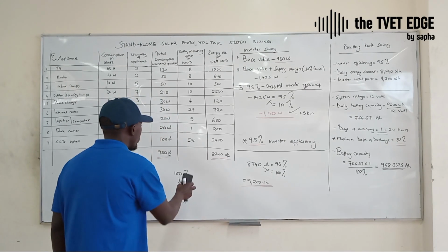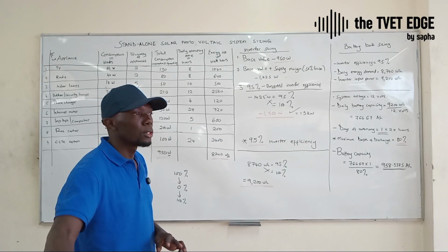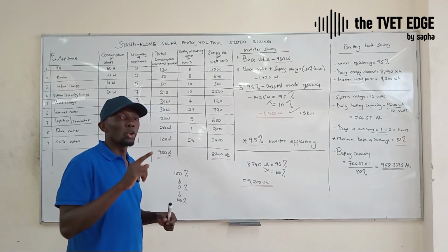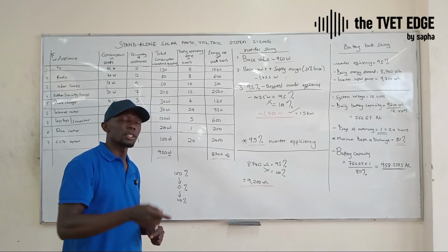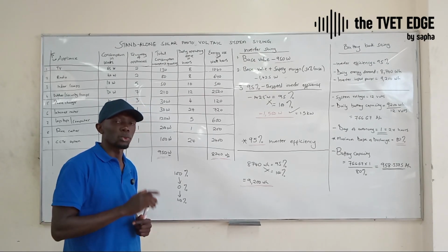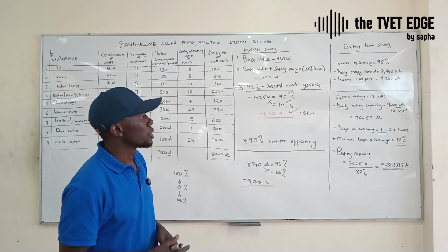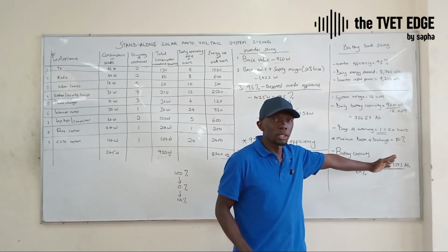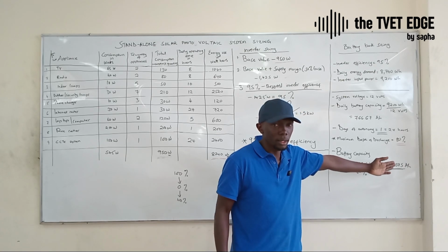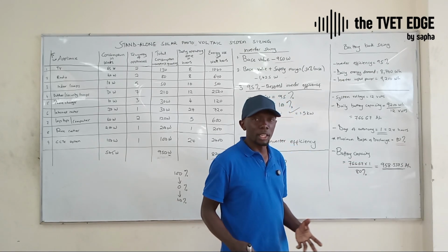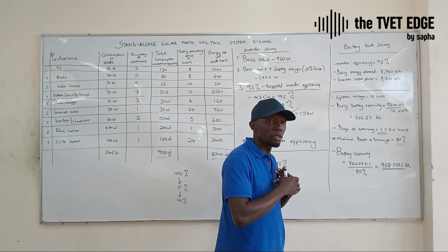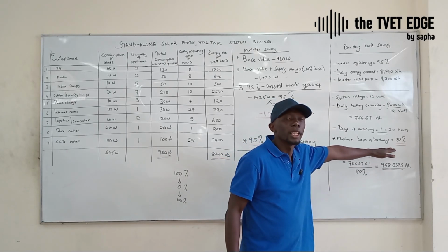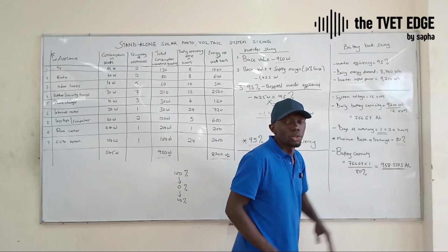And here is why. You are not allowed to drain your batteries to 0%. You are never allowed to size a system that will go all the way to 0% and then start the next morning at 0 to recharge back to 100. No. In most batteries, you are allowed to discharge 80%. That means you can take your batteries to as little as 20%. And in modern inverters, some of them have even been programmed to not allow you to discharge beyond 80% depth of discharge.